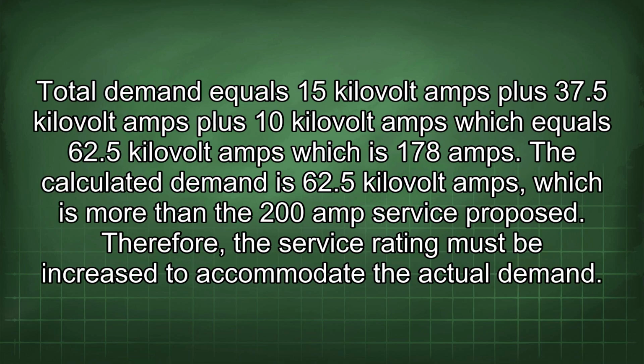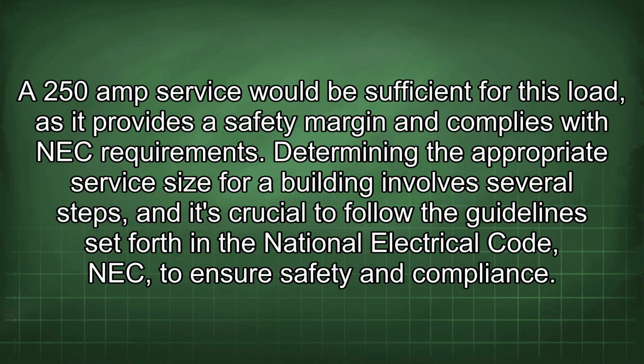Total demand equals 15 kVA plus 37.5 kVA plus 10 kVA, which equals 62.5 kVA, which is 178 amps. The calculated demand is 62.5 kVA, which is more than the 200 amp service proposed. Therefore, the service rating must be increased to accommodate the actual demand. A 250 amp service would be sufficient for this load, as it provides a safety margin and complies with NEC